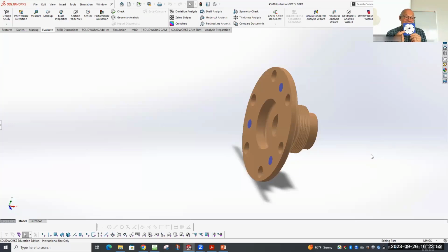That might not matter. And in this case, it doesn't, because this is completely symmetrical. It doesn't have a keyway in it. There's nothing on it that would index it. So it doesn't matter where this goes, as long as when I turn it, it's sitting on those pins in the right place. So 5 degrees of freedom, then this part can be measured.